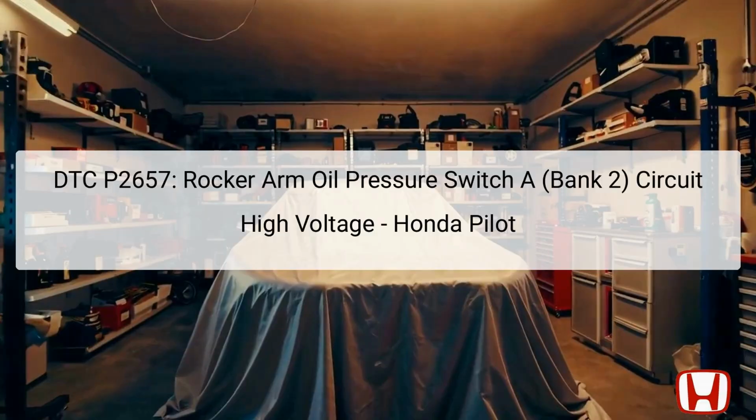The P2657 Diagnostic Trouble Code, DTC, indicates a high voltage condition in the rocker arm oil pressure switch A circuit for Bank 2 in a 2016 to 2022 Honda Pilot. This particular switch plays a critical role in the engine's variable valve timing and cylinder management system. By measuring oil pressure, it helps regulate the rocker arm's function, thereby enhancing engine performance and fuel efficiency.